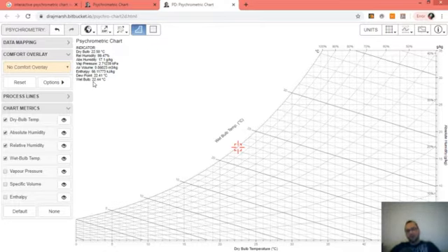As I have mentioned in class, the wet bulb temperature is used to assess the effectiveness of evaporative cooling, and usually is measured with a thermometer covered with a wet sock. A wet sock to imitate 100% relative humidity, a fully saturated air.